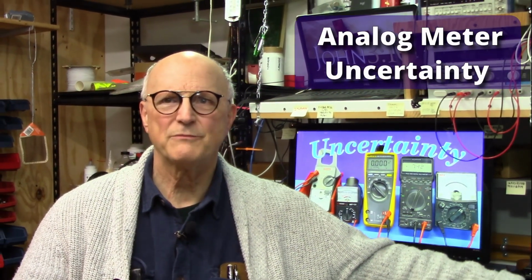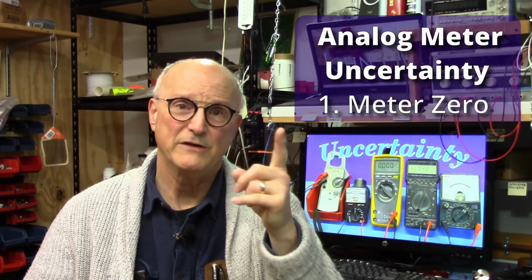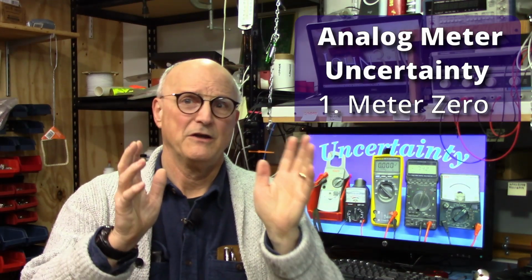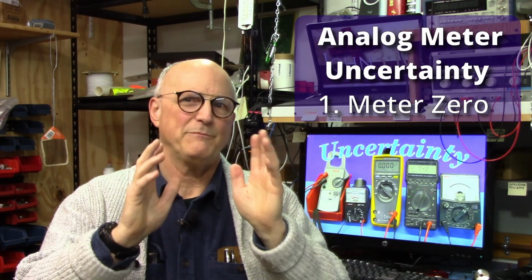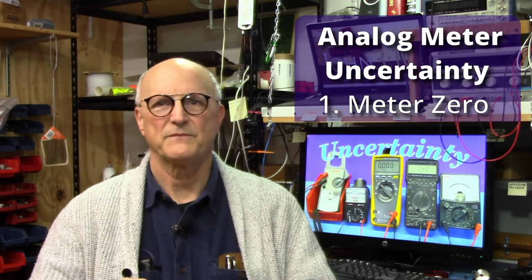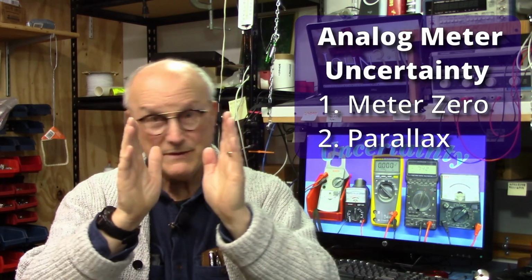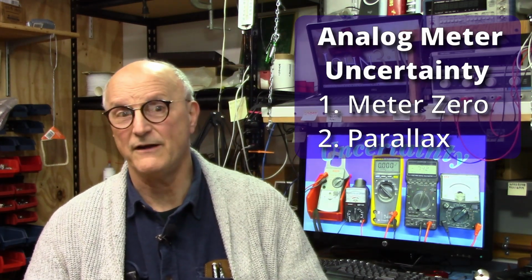With an analog meter, there are two other things that contribute to measurement uncertainty. The first is meter zero. In other words, when nothing is connected and the meter is turned off, and it is physically in the same position it will be in when making the measurement, is the needle resting on the zero? The second is parallax. Are we positioning ourselves properly to read the value off the scale?